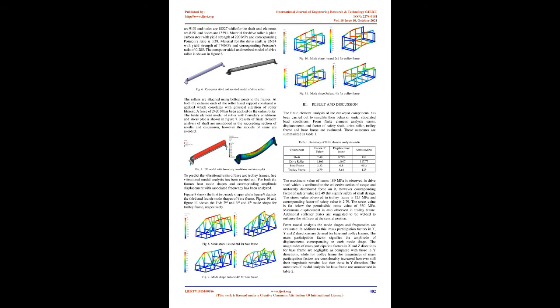The finite element analysis of the conveyor components has been carried out to simulate their behavior under stipulated load conditions. From finite element analysis, stress, displacements, and factor of safety of shaft, drive roller, trolley frame and base frame are evaluated. These outcomes are summarized in Table 1. Table 1. Summary of finite element analysis results. Component, factor of safety, displacement in mm, stress in MPa.